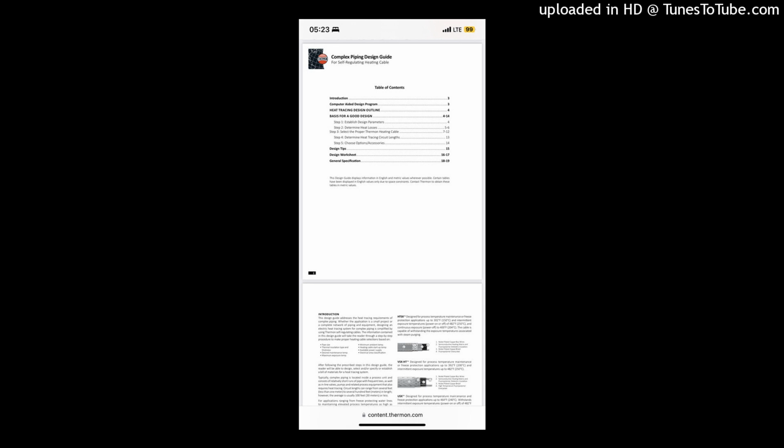Step 2. Determine heat losses. Using information gathered in Step 1 and based on heat loss chart tables, computer design programs, CompuTrace. Select the proper thermal heating cable based on application requirements: maintain temperature, maximum exposure temperature, watt density requirements, power output at maintained temperature, electrical design, available voltage, circuit breaker capacity, cold start impact, approval requirements, hazardous area approval, code requirements.